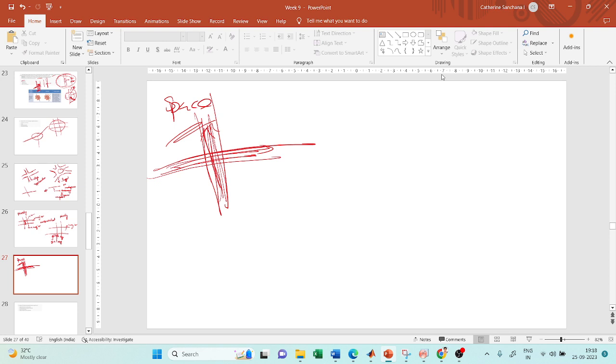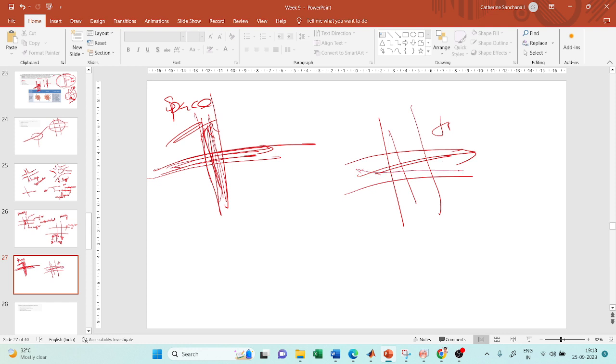The other one is the time separated intersection, which we just saw. For a time separated intersection, the best example is a signalized intersection. Now you have two roads crossing each other. Both will not travel at the same time. Both will use the same space, right? Vehicles traveling on this road will use this portion of the roadway, and vehicles traveling in this direction will use the same space, but the only difference is they will be separated by time.